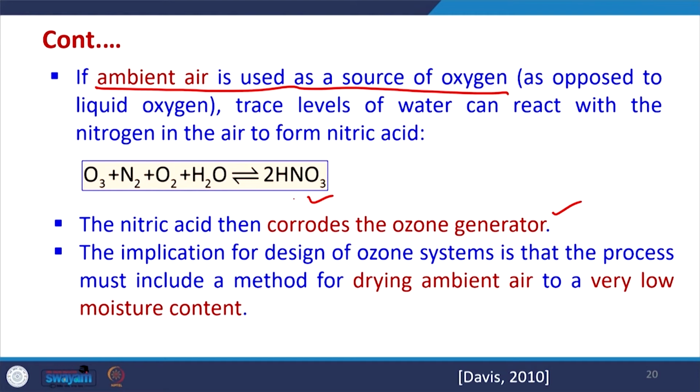Thereafter, the ozone generated is passed through the water and diffused into the water, and the pathogens in the water get oxidized. Along with the pathogens, if other organic species are present, they will also get destroyed by the ozone.